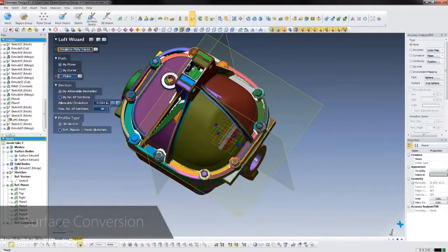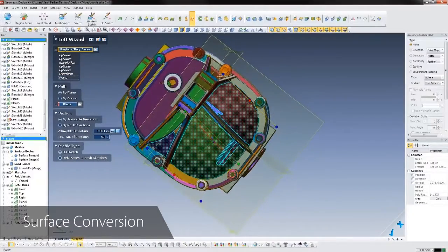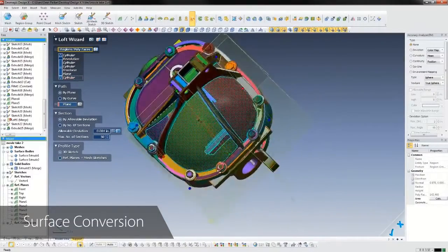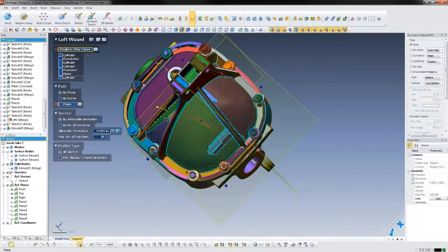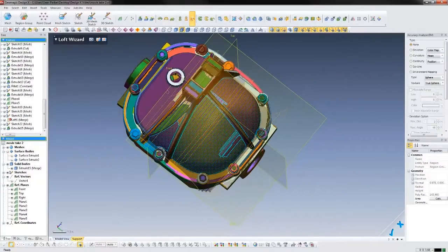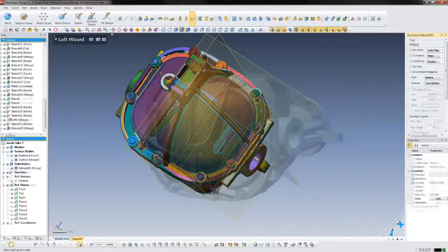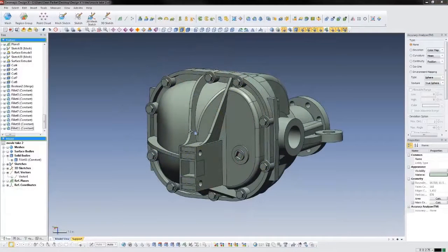Design X also handles complex surfaces with ease. Here we'll fit a high-accuracy surface to a region of the mesh. This can be done with a mesh fit surface, or a loft, or a sweep. The software has the tools to make whatever surface you need, and it will do it automatically from the scan. Surfaces can be stitched together into a solid, or used to cut bodies, and their quality can be checked with the Accuracy Analyzer. Finishing touches like fillets, chamfers, and bolt holes are all easy to create. Design X will automatically calculate the fillet radii, hole locations, and size from the scan data.